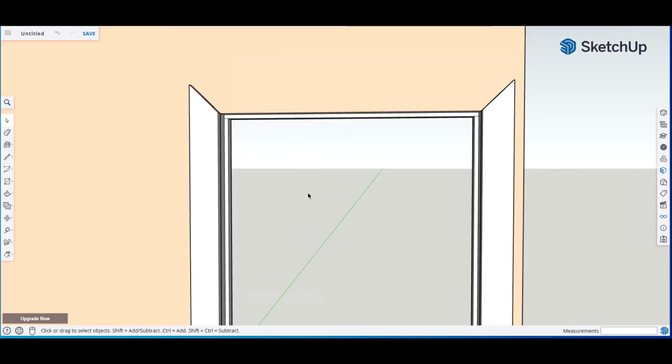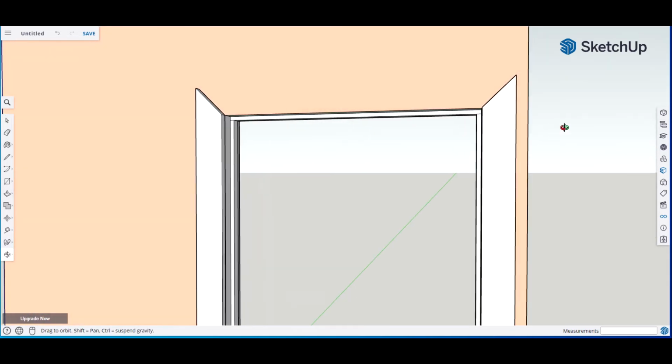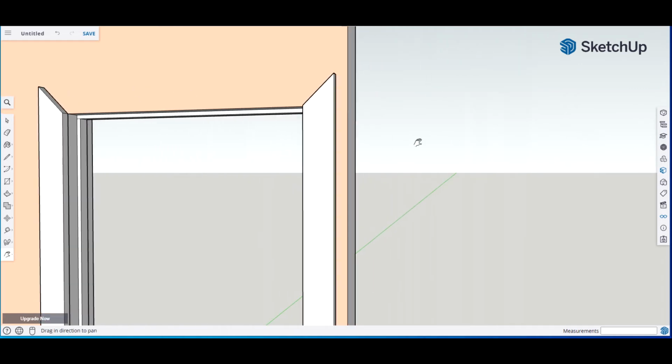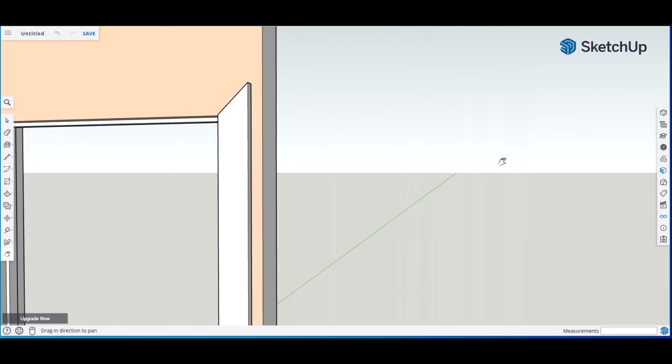So next is measure the total width of this upper door molding. So we're going to hit T anywhere along the line here, and it's 39.25. Space bar, and now let's hit H, and we're going to pan. Hit H. We're going to slide over, and now let's create our top molding.